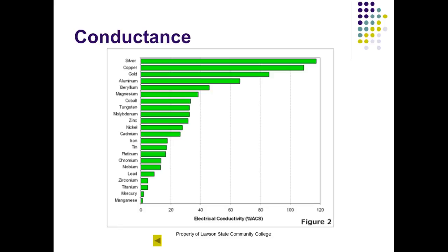If you have the opportunity to get into one of these downdrops, where the downdrop is aluminum and they connect it to the copper, if you pull that tape off, there's going to be this brown goop in there, and that's that antioxidant. You can buy it at Lowe's. You've got to be real careful because a lot of your older houses, like my son's house, were built with aluminum wire.